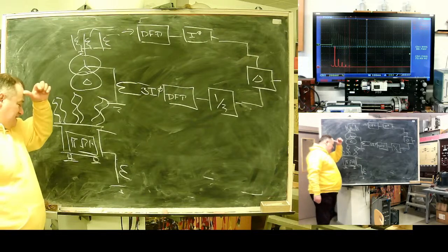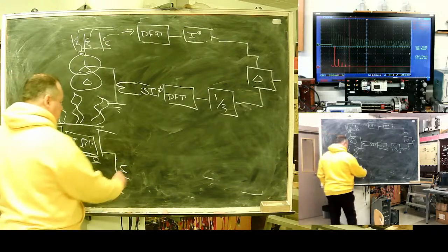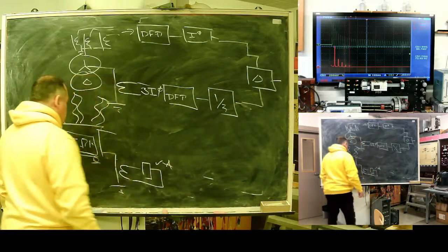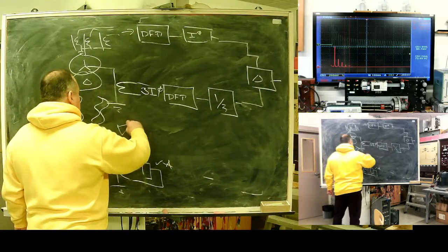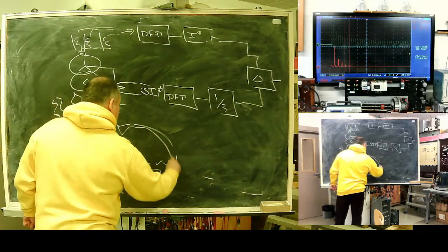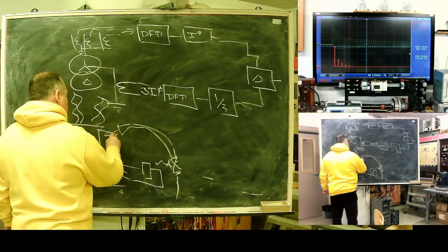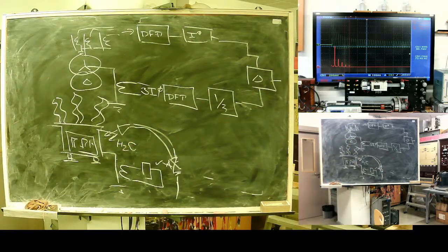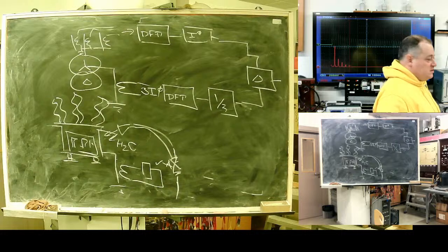If you see current here, what will you do? This relay activates fire extinguishing. If you observe current in this earthing link, the fire extinguishing system should be activated. It means internal fire.